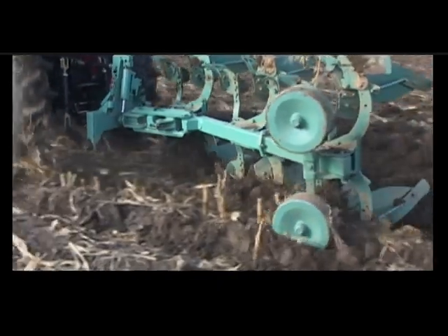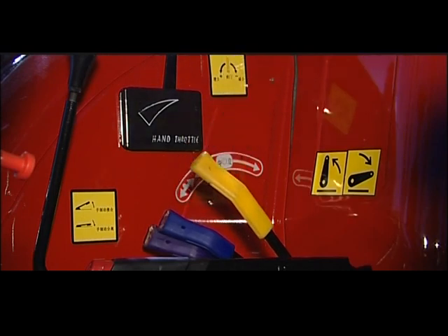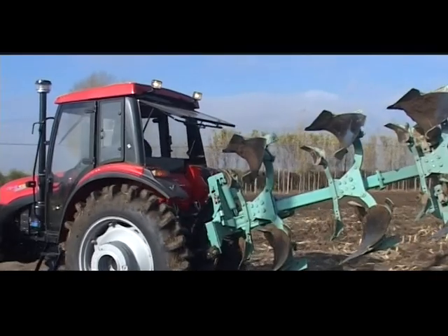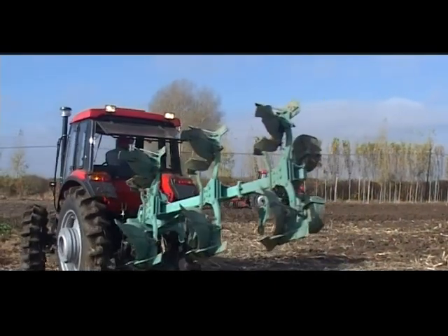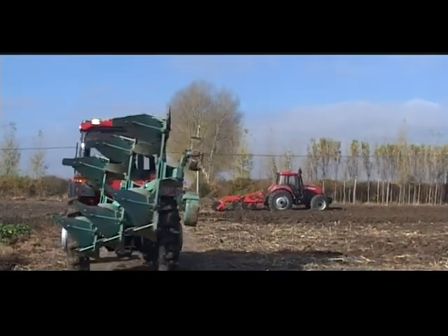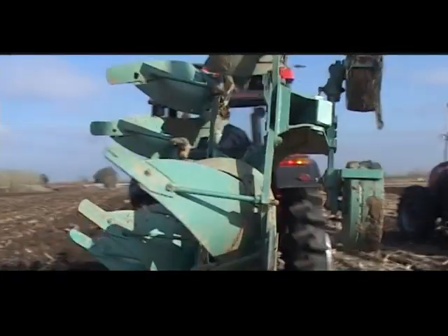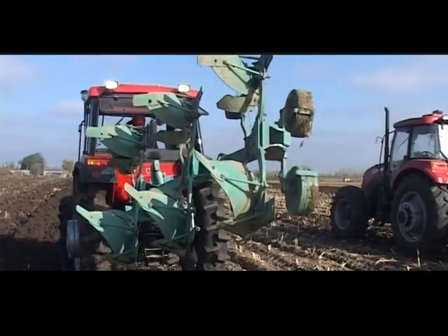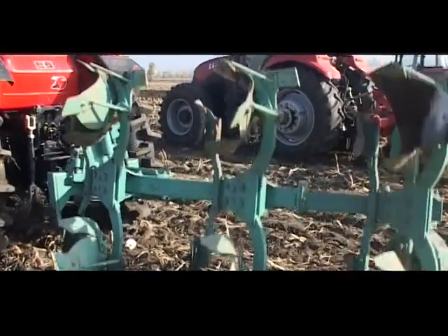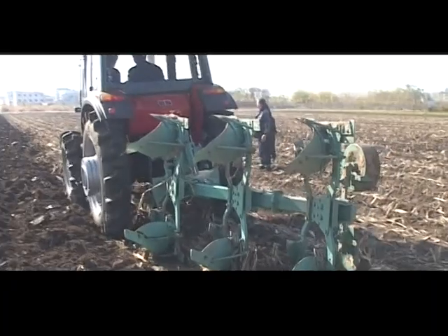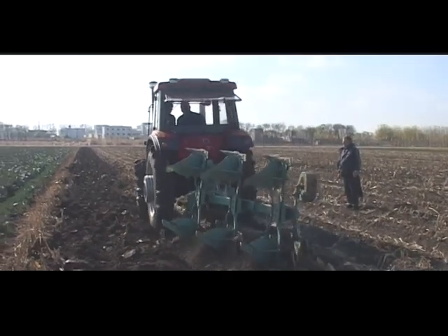When the tractor works with an implement with a depth wheel, it shall work in floating position. When the tractor turns back at the end of the field, the implement must be lifted away from the ground before turning, and the turning speed shall be no more than 5 kilometers per hour. Otherwise, it may damage the implement or tractor hitch device. After turning, when the tractor is driving in a straight line, slowly move the implement down into the earth.